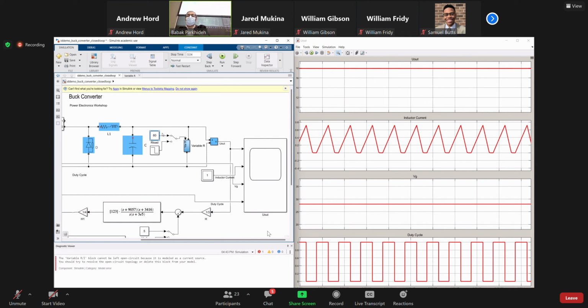Anyways, so here, what I wanted to show you is that with this continuous conduction mode, essentially you have 3 sub-circuits. You still need to write down the volt-second balance. Volt-second balance and charge balance are exactly the same. But now instead of having 2 sub-circuits, you have 3 sub-circuits. In the first sub-interval, the switch at position 1, or the active switch, conducts. In the second sub-interval, the diode or the switch at position 2 conducts. And you have a third sub-interval in which none of them conducts. There is no current in the circuit.